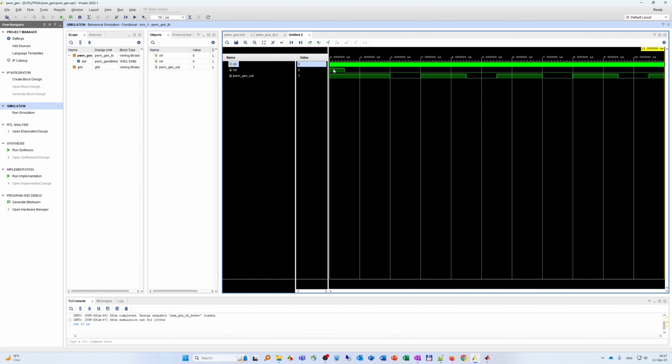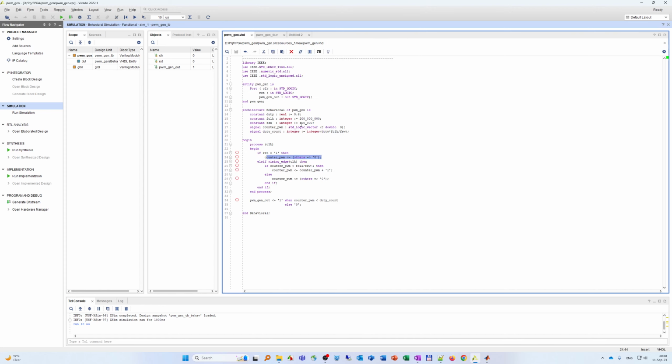So as long as the reset is logic high, the counter stays at 0, and once it's released, the PWM count starts from this point. Then it's gonna count until this duty count, PWM high and then low, PWM high and then low. Let's change our duty ratio here. Let's make it bigger, let's say 0.85.